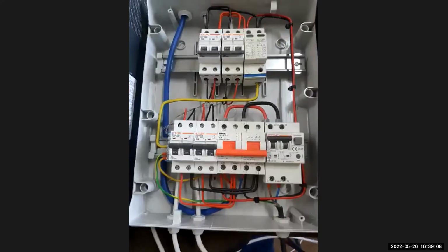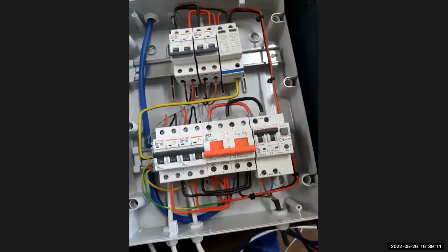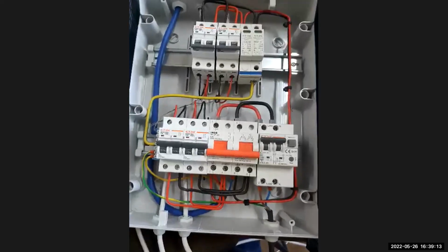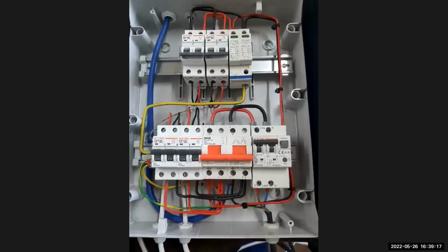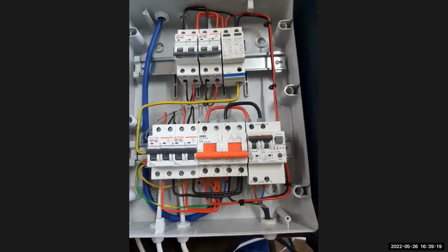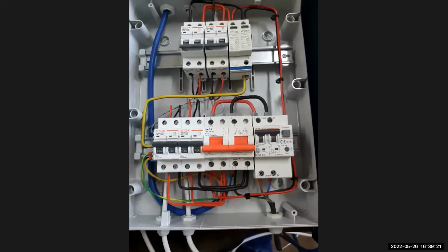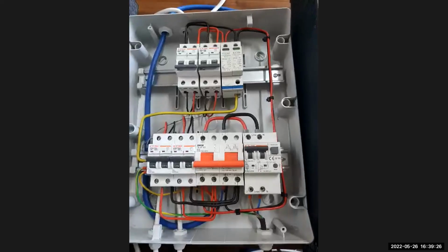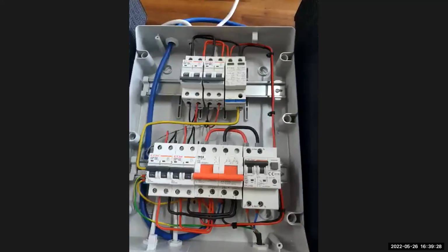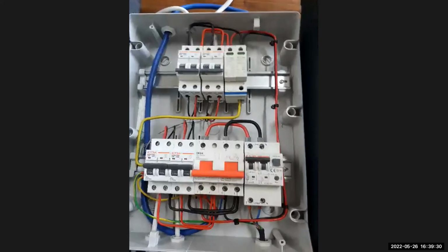And then at the bottom, at the beginning, I also said about the settings of the number 21 for the parallel settings. Always remember you have to do it on all your inverters. You have to go physically on all of their screens to say setting 21 is a one-phase system or a three-phase system to give this inverter the right position in the parallel system.